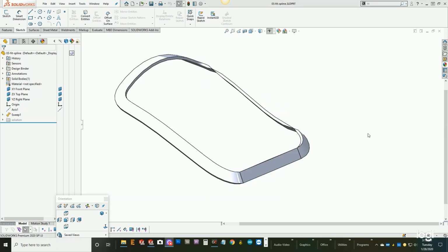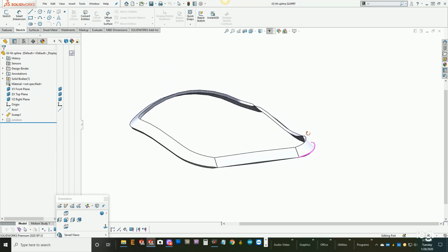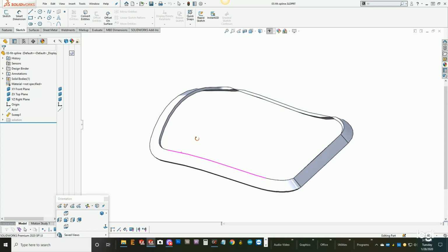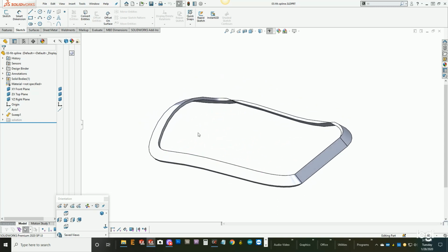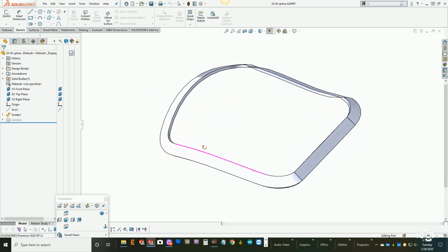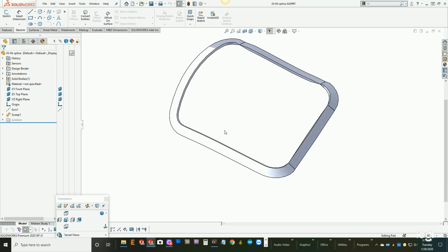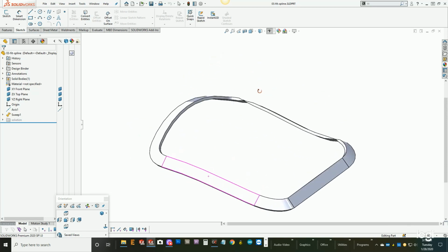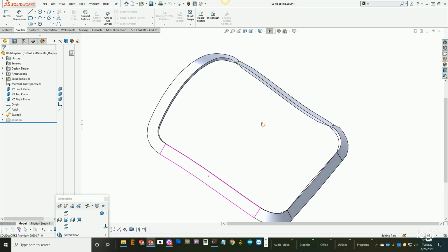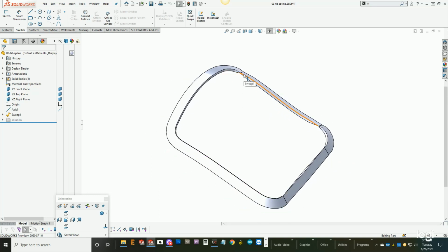This next tip has to do with how I can make my features work better. And one of the tools in my arsenal to make that work, especially for swept features, is to try using a Fit Spline to rectify issues like what you see right here. So this is a gasket that sweeps around a 3D form, and you can see the sweep is not resolving correctly here on the sweep geometry.